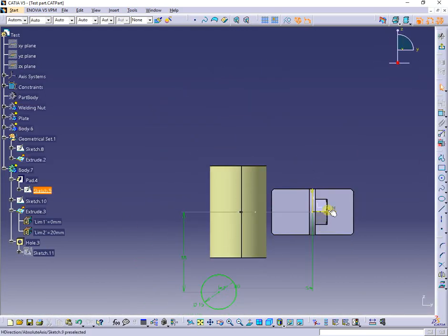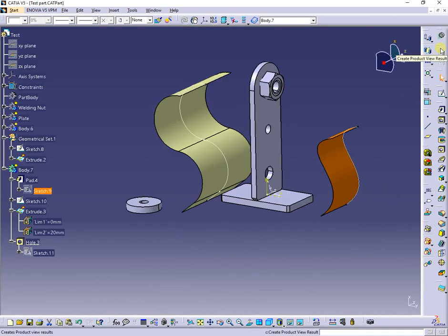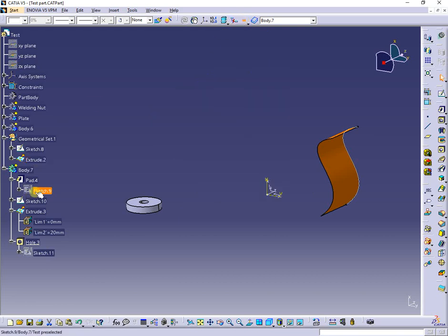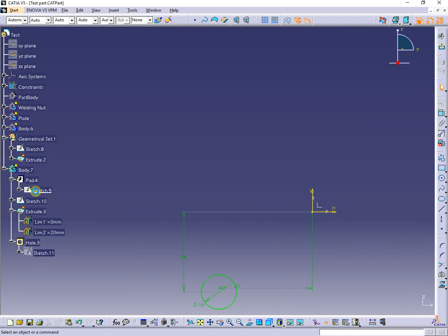If all those options are unselected, in the current sketch, all the geometry contained in other bodies or parts is visible. If any option is selected, in the sketch the corresponding geometry for that option is deactivated and not visible or selectable.